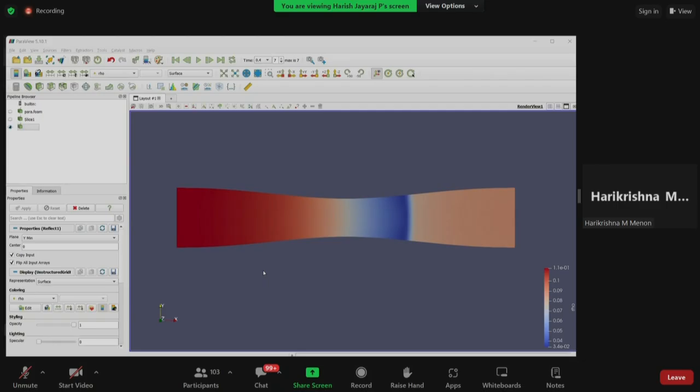Okay. Thanks. The professor in the previous session showed a flow over a wedge or some kind of a ramp, a deflection. So is it possible to solve a similar problem using this solver? Yes, we can do the exact thing using this solver. All you have to do is replace the mesh made in blockMesh, and you can import any mesh from software like Salome, Gmsh, or even Fluent Mesh. You can import such meshes into OpenFOAM and you can run it.